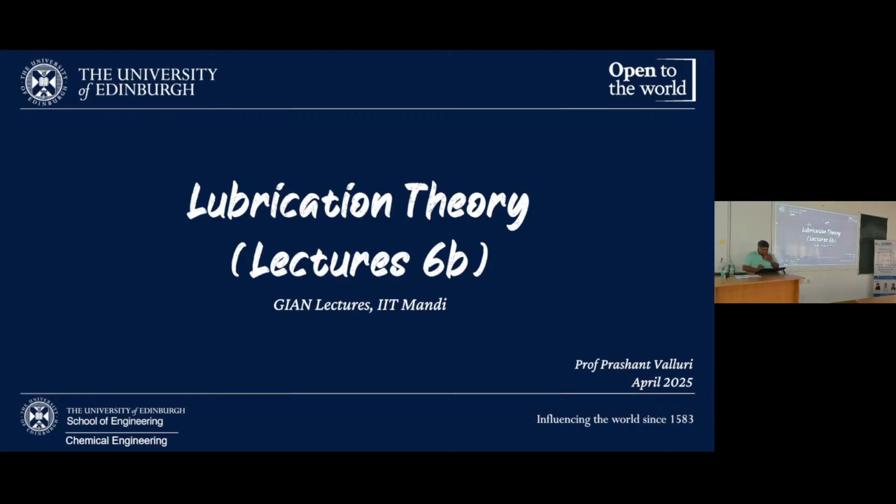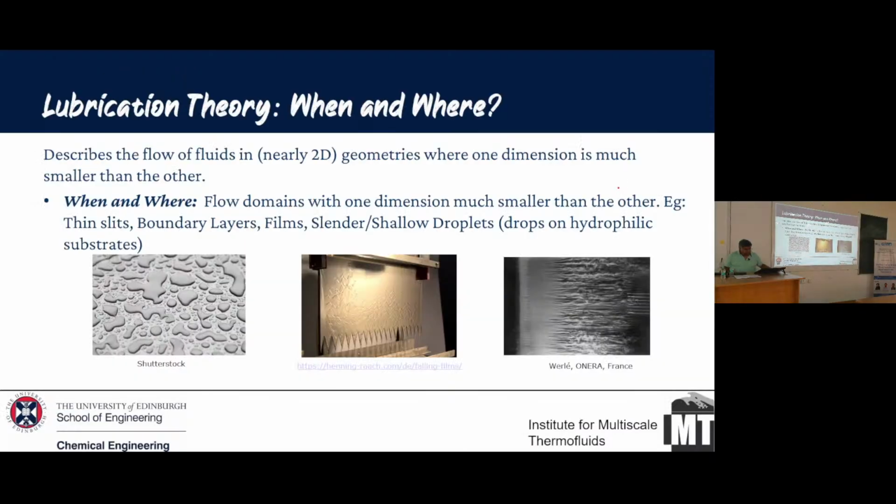Now what we're going to do is look at another method which we use for droplets. It's called lubrication theory. Okay? And in lubrication theory, it's important to understand where we can use it. Lubrication theory is a very, very special theory. It is applicable for flow domains which have very small height with respect to length. So H is much, much smaller than L. Okay? It's a very thin film.